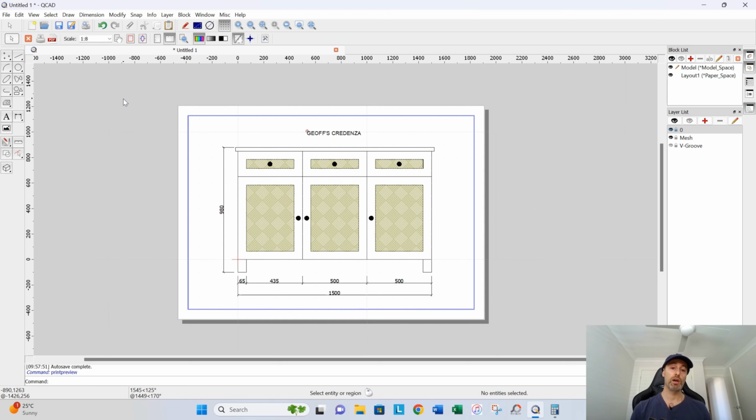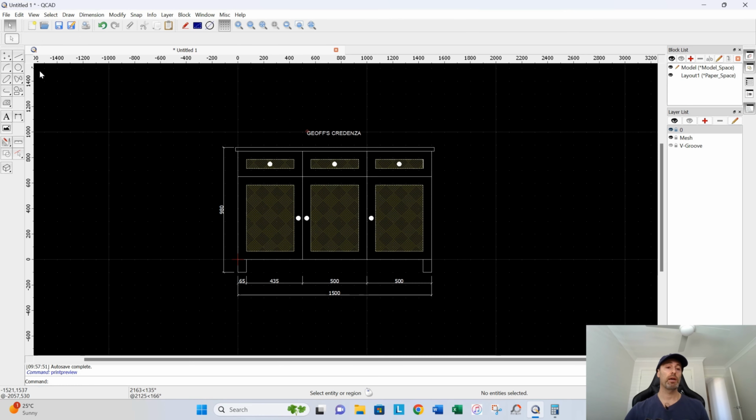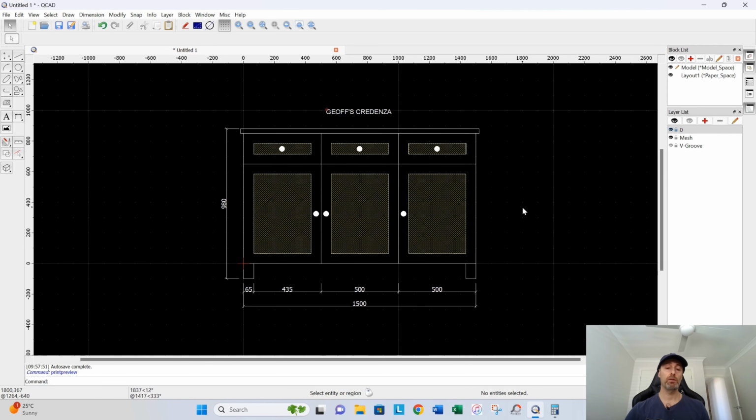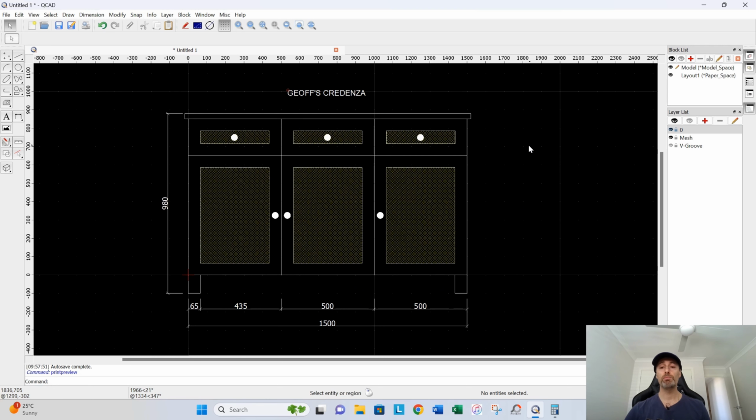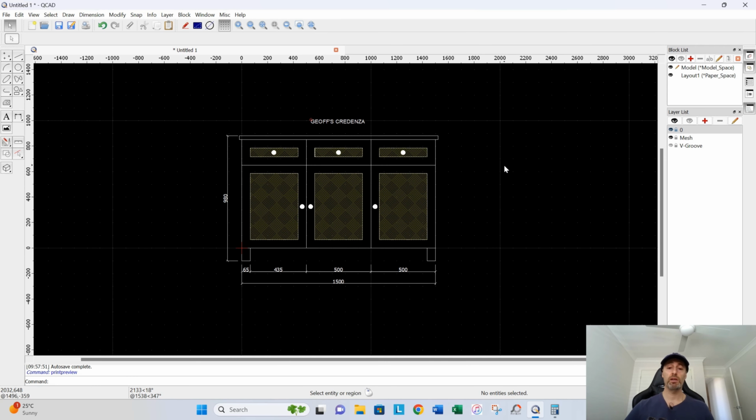I haven't even indulged in the depth of this program. It's so complex. But you can see that just using some of those basic tools that I've used, you can draw some cabinetry or joinery and design some stuff, and then print this, which will help you put it into production in your workshop. I hope this video has been helpful to some of you, especially if you're a beginner or you're new to CAD programs. If you've already used QCAD, it might be really helpful to you to draw some cabinets, hopefully.